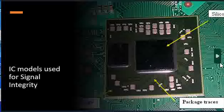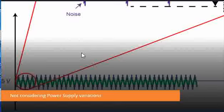And second thing, when we are doing the signal integrity analysis, SI engineers don't consider the power supply variations that might come when the final PCB and assembly is done and the board is actually powered up.